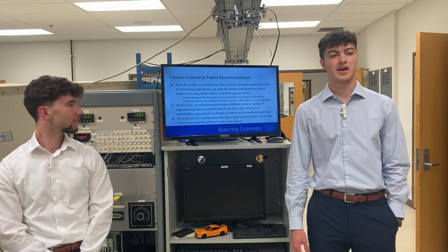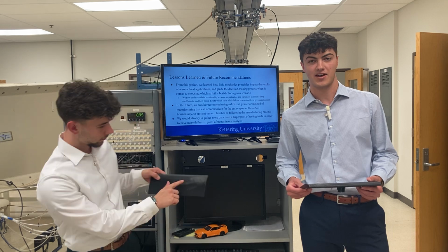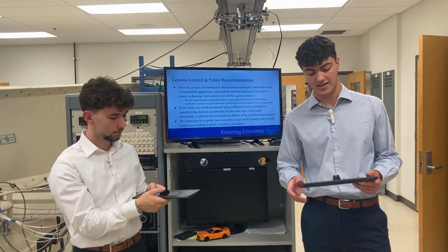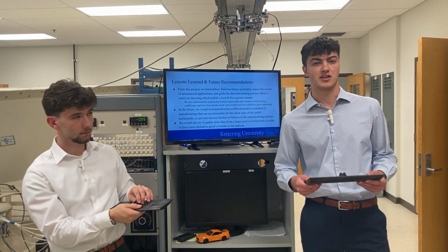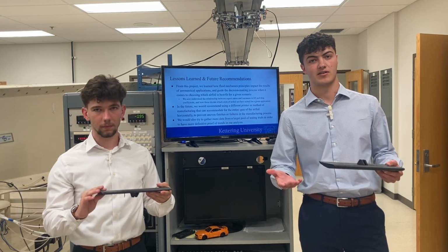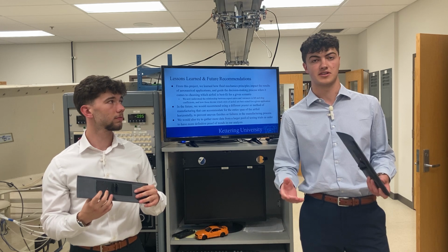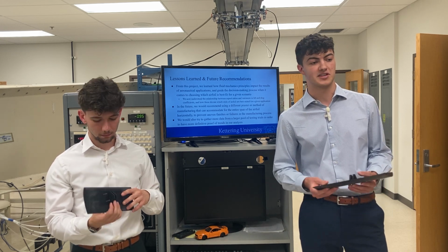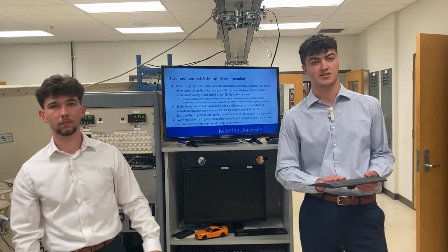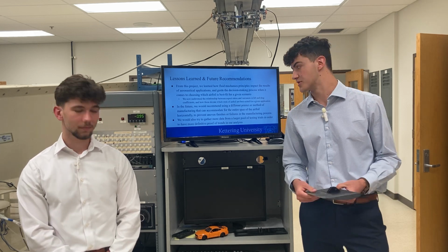In the future, we would recommend using either a different manufacturing technique or a different printer style when making these. Talking with Ray Rust, we basically decided that in the future we would either use a printer with a larger bed that would allow the part to be manufactured flat, that would leave a better surface finish without having to rely on supports to hold it up. It would also lead to less failures. Or another option we discussed was using metal and having these laser cut for the smoothest finish possible and most accurate, but due to time constraints, we didn't decide to pursue that option.